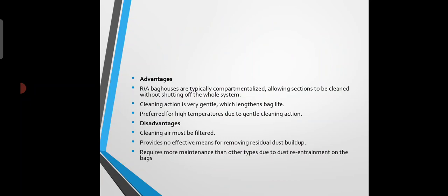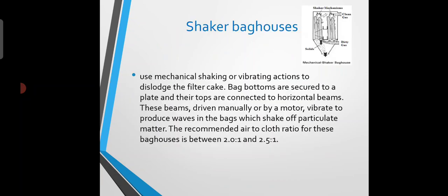Advantages are they are typically compartmentalized, allowing sections to be cleaned without shutting off the whole system. Cleaning action is very gentle, which lengthens the life of the bags. Preferred for high temperature due to gentle cleaning action. Disadvantages are the cleaning air must be filtered, and it provides no effective means of removing residual dust buildup.